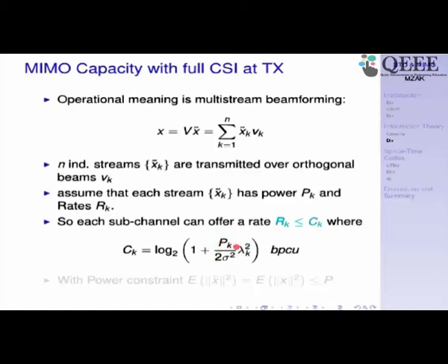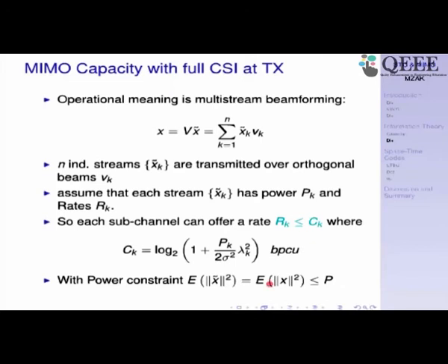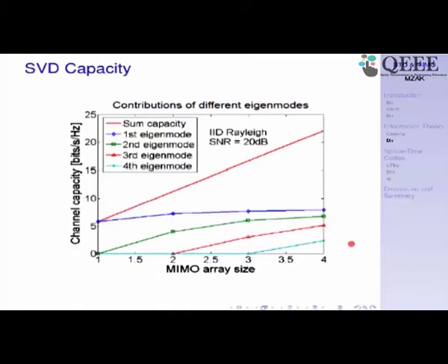Okay, so I have just calculated the signal to noise ratio here for each of the channels that was derived in the parallel channel in the previous slide, and I put it into the expression here. Now there is one additional constraint. Remember that. What is that? The sum total power is going to be less than P. So you can also see it as the summation of Pk is less than or equal to P. That is the constraint. Now next slide.